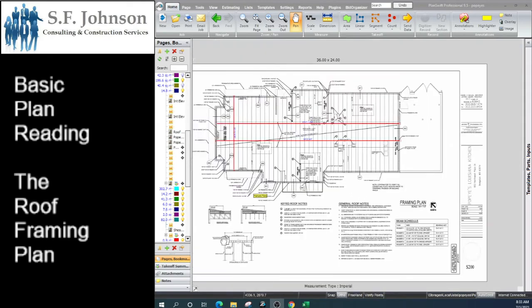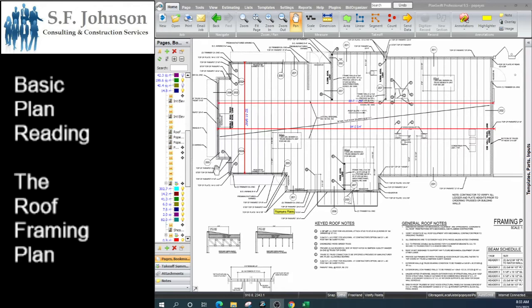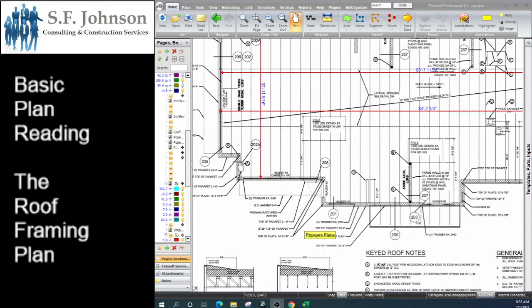And also in a cost book, you'll add a certain percentage for connections. It's usually about 15% of the cost of the material that we add just for the connection, so we don't have to go through there and count each connector one by one. 15% of the cost of all of the structural members would suffice for the additional cost for the connectors.